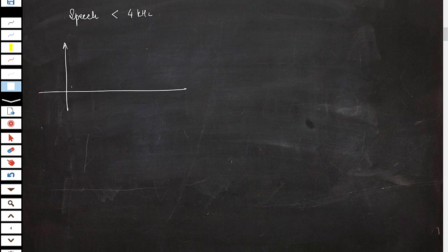To understand the next part of the exercise, we should know that although speech will be less than about 4 kilohertz, if I took a recording of somebody singing without any musical instruments, and still the pitch goes up and down, normally the frequency content of such a signal should appear something like this. A lot of it is focused on the lower frequencies, and gradually higher frequency content will start going down. If you have musical instruments playing, musical instruments have higher frequencies and their overtones as well, you will notice that this may change to something like this. It has more higher frequency content, but still if the audio is very loud, most of the content is focused on the lower end.